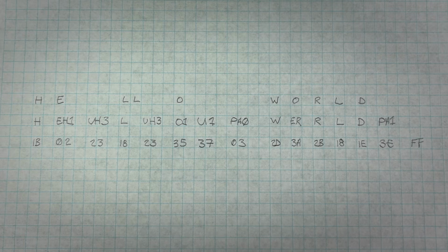Don't let the fact that these are hex numbers confuse you. To the Votrax chip, they represent sounds, just like the hex numbers in the program itself represent commands and addresses and numeric values. The 6808 only understands one thing, numbers. Their meanings change depending on where they appear in a program, so it's up to us to keep track of which is which. The comments column is our friend.